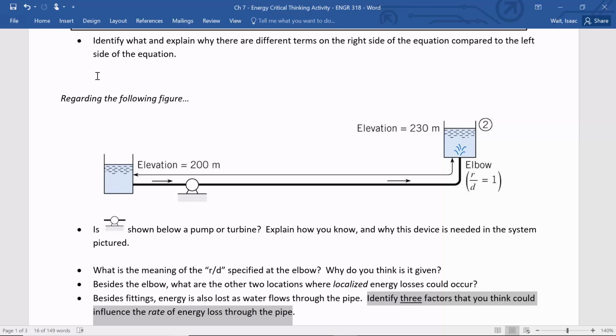Smaller cross-sectional area. And what does that do to the velocity when you're trying to force a lot of flow through a smaller cross-sectional area? It increases the velocity, because we know V is Q divided by A. So if you have small A, then you have big V, right? So here is the equation. This is the Darcy-Weisbach equation. It tells us the rate of loss. For a 1 meter length, if the length is constant, then a high velocity will give you a high friction loss.